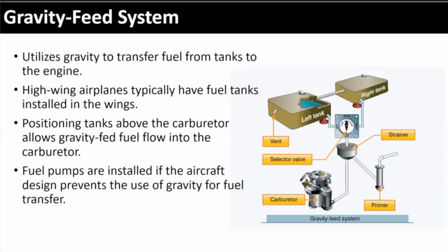It doesn't work. So typically, what are we going to have in a gravity fed system to facilitate those times when gravity isn't doing its job? A pump. Exactly. So even though we call it a gravity fed system, they all have an auxiliary fuel pump, just like on the Cessna aircraft downstairs, an auxiliary electrically driven fuel pump that you turn on during the flight.